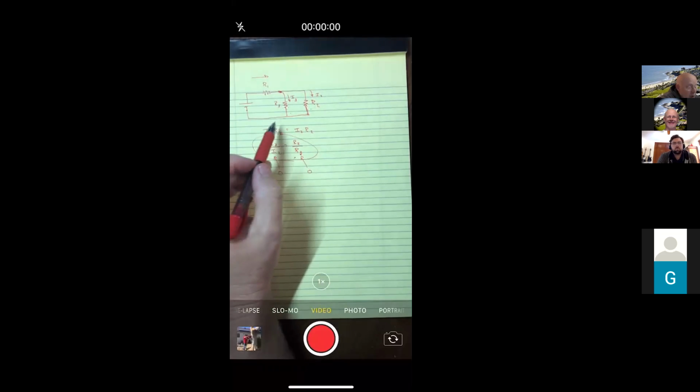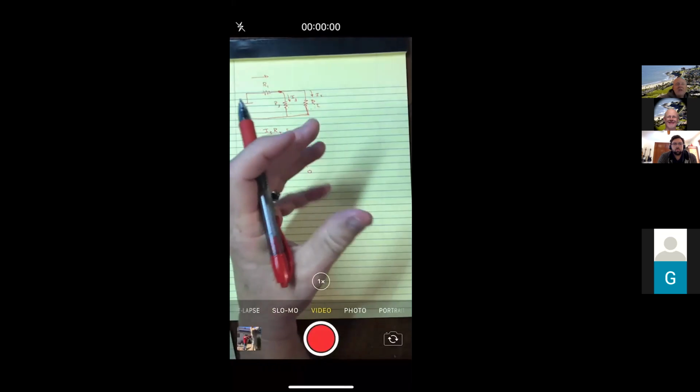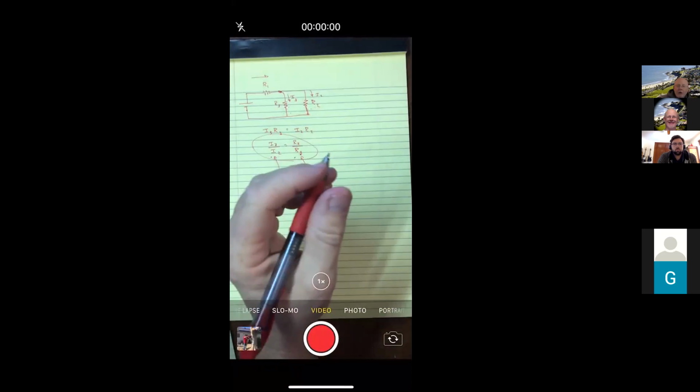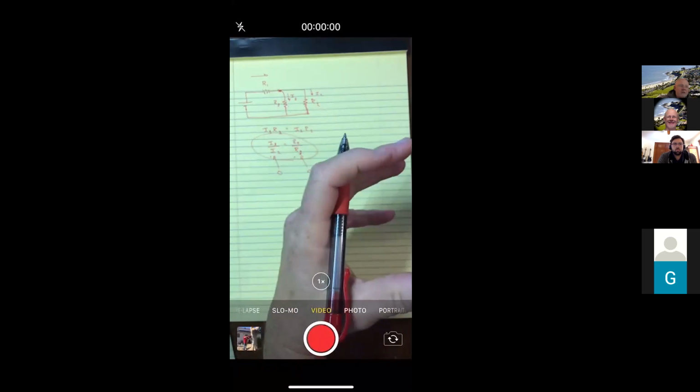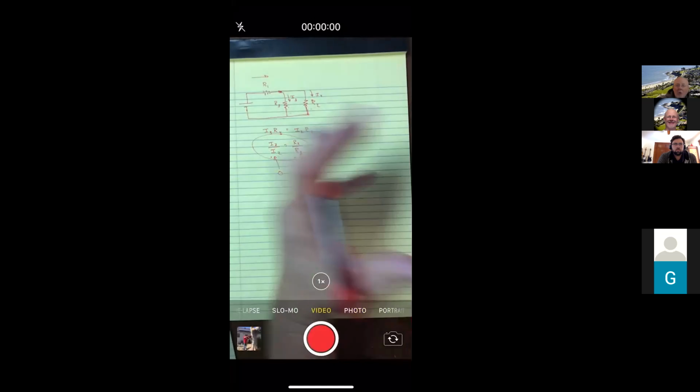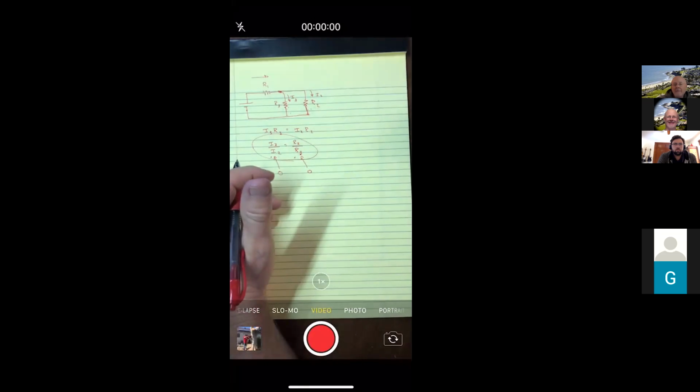If you lower resistor number 3 all the way down to 0 resistance, that is the case, and only the case, where you'll get all the current going through the least resistance. So to say the current goes to the least resistance, like I said, is a little misleading. All the current goes through the resistor if it has 0 resistance, but that's the only time that occurs. Otherwise, it splits in some kind of ratio.